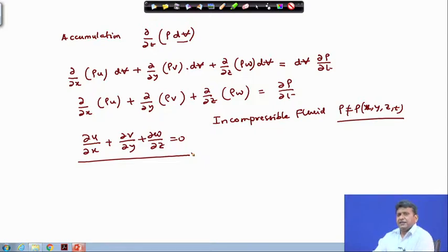There is a very interesting catch. Actually, even if you have an unsteady flow with an incompressible fluid, you will still get this form of the continuity, because your right hand side del rho del t term cancels out because of the definition of an incompressible fluid, which is rho does not change with time, right. So, this is very interesting. People have a feeling that this form of continuity is valid only for a steady state flow. That is not the case. Steady or unsteady, the moment you have an incompressible flow, this form of continuity remains valid, right.